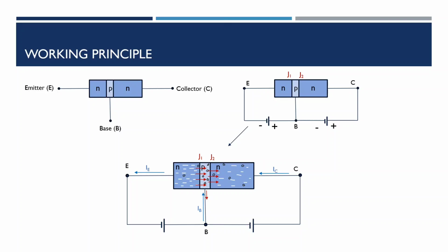Since the base layer is p-type, and we know that the minority carriers can move through the barrier into their preferred material based on the energy they have, the electrons in the p-type are minority, so they will just move into the n-type where they can become the majority. So in this case, the sudden rush of the electrons will want to move into the n-type collector material.